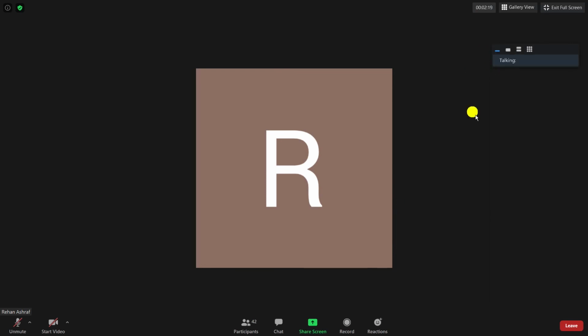If it is at the property limit, it would be on one side only, right? Sometimes if there are a number of columns, we go for combined foundations, but normally in houses, there are only one or two columns. We provide isolated foundations for such type of columns, and there is no problem.